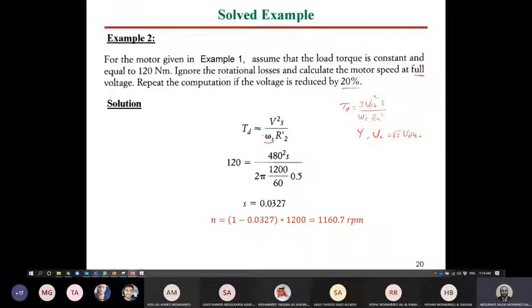Omega S equals 2 pi over 60 multiplied by RPM, which is 4 pi F over number of poles. So omega S equals 4 pi F over number of poles, which is equal to 2 over P multiplied by omega S electrical, which is 2 pi F. Okay? If you substitute by 2 pi F here, you will get the mechanical speed. So omega S here, we are working with mechanical speeds all the time in the machine models.